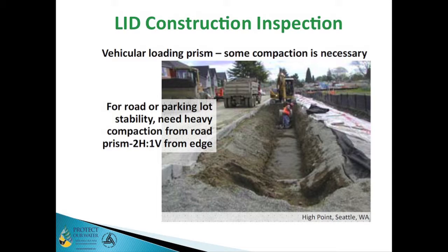The other obvious caveat to this is utilities. And again, the designer is going to always go and try and identify all the utilities. But when we start doing this and we find out that there's utilities we didn't know about down there, we need to stop and put a little thought into, do we really want to infiltrate a bunch of water on top of an old clay segmented sewer lateral, or a gas pipe, or an electrical vault, or what's there. So need to be aware of what we see in the field and how it might impact the project as we move forward.